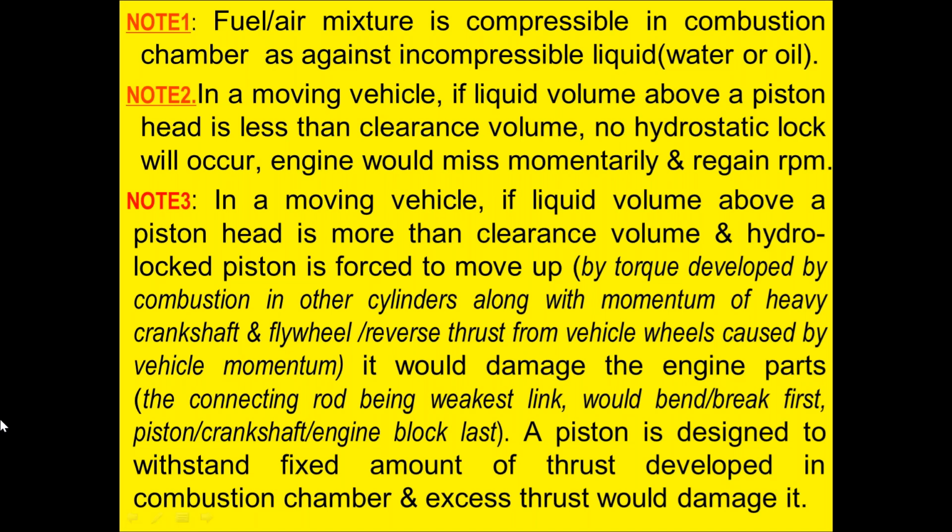Note 3. In a moving vehicle, if liquid volume above a piston head is more than clearance volume and hydrolock occurs, the piston is forced to move up by torque developed by combustion in other cylinders, along with momentum of the heavy crankshaft, flywheel, and reverse thrust from the vehicle wheels caused by vehicle momentum.